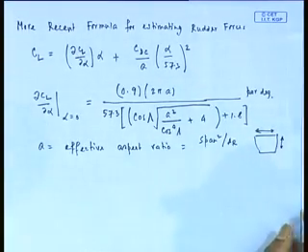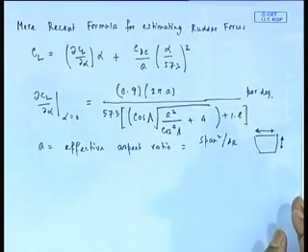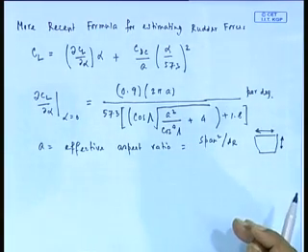What is the typical aspect ratio of a rudder of a ship, do you think? Just in this discussion, let me ask you, approximately how much is the aspect ratio of a rudder, in which order? Is it 0.2, 0.3, or 1 or 2? It is 1.3, 1.5, in that order. So keep this in your mind, because next class when we talk a little bit about ship hull derivatives, we will find that the ship can be treated as a lifting surface of very low aspect ratio, because T by L becomes the aspect ratio, but this is around 1.3.